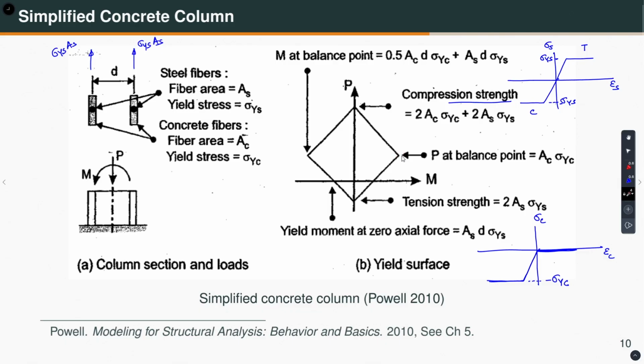We have also discussed earlier what the balanced point is. Now, I want to calculate what is the force and what is the corresponding moment at the balanced point. Okay. So, to do that, let us first see what is the stress distribution. So, we are assuming the direction of bending moment is like that, right.